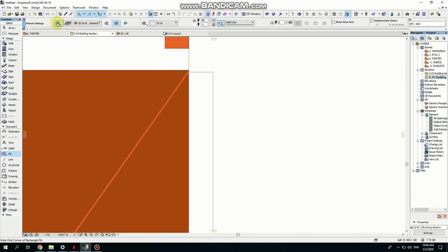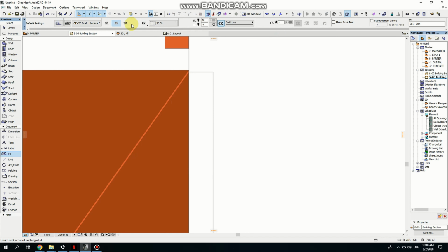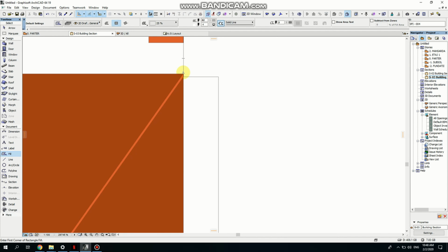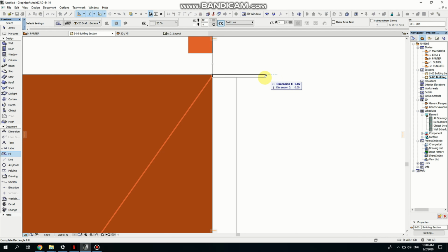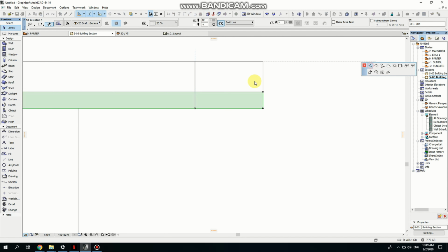So I'm going to make a small handle. I'm going to use my fill. Yeah, and it's on geometry method rectangular. And I'm just going to make something. So 2 millimeters thickness. I'm going to create a point. We're holding shift to make sure the line is going to be straight. Then create another point here, and I'm dragging this down.